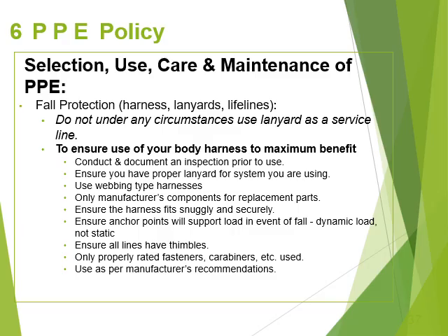Do not, under any circumstance, use your lanyard as a service line. To ensure the use of your body harness to the maximum benefit, conduct and document a pre-use inspection before putting on your harness. Ensure you have the proper lanyard for the system you are using. Use webbing type harnesses that have greater strength factors as opposed to leather. Use only the manufacturer's components for replacing parts. Ensure the harness fits snugly and securely as per recommended directions. Ensure that the anchor points will support the load in the event of a fall.